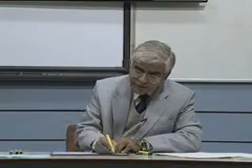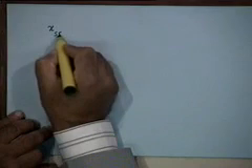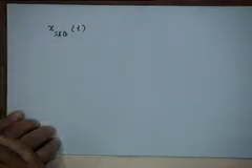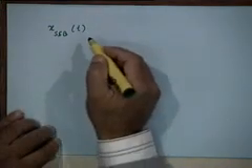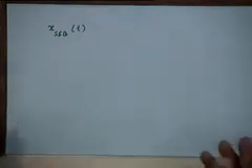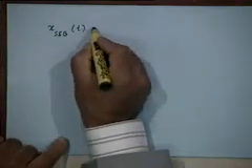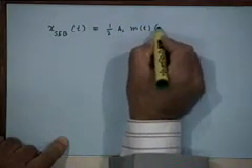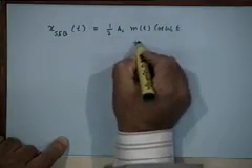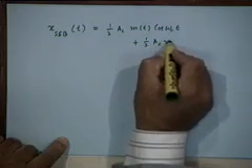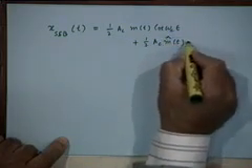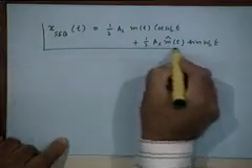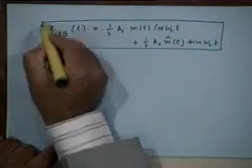So that gives me a closed form mathematical expression for the SSB signal, the single sideband signal, in terms of the message and the carrier, just like we had for the DSBSC signal, and that is equal to half AC mt cosine omega ct plus half AC m hat t sine omega ct, right? A very neat and interesting expression.